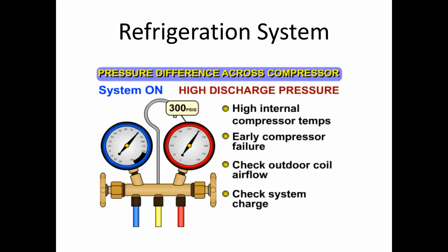So airflow, again, indoor and outdoor, is very important. Every time you go look at a unit, before you hook your gauges up, clean the outdoor coil and check your indoor air.